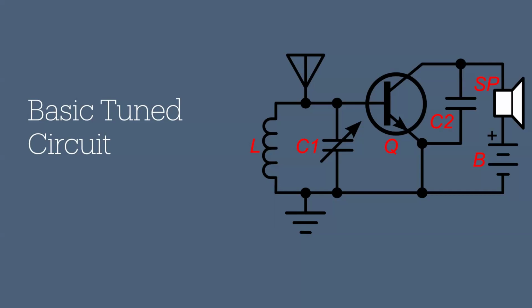The inductor, L, stores energy in a magnetic field. The capacitor, C1, stores energy in an electric field. As you charge the capacitor up, the voltage builds up and pushes the current back to L. Then the magnetic field builds up in L, and the impedance of that part builds up and pushes the current back to C. So it oscillates backwards and forwards. It's a resonance circuit. Depending on those component values, there is a frequency at which it naturally resonates. That frequency is held in the resonance section of the circuit between the capacitor and the inductor, and all other frequencies are allowed to bleed through to Earth. So now you've picked one frequency out of a whole range of frequencies that might hit the antenna.